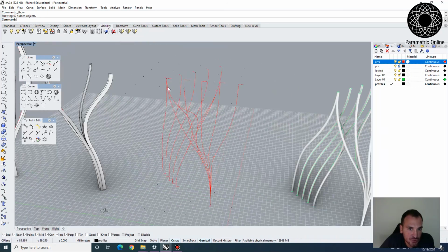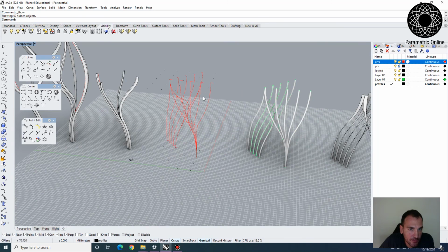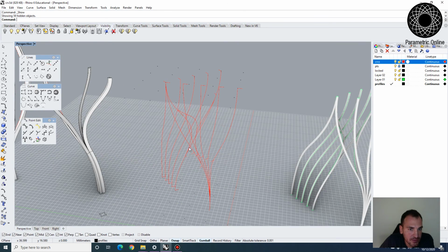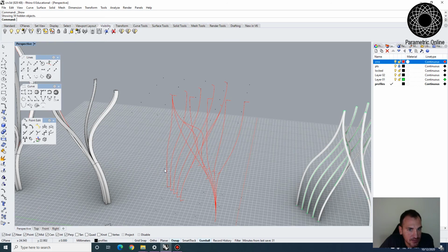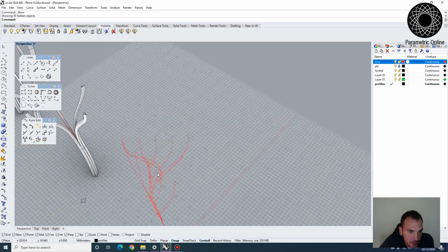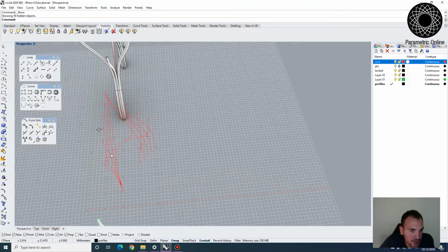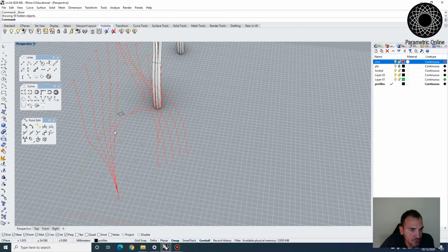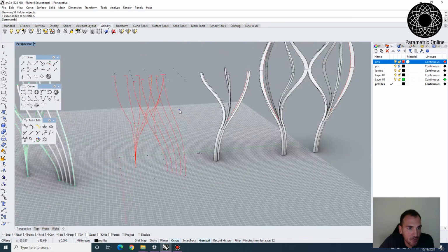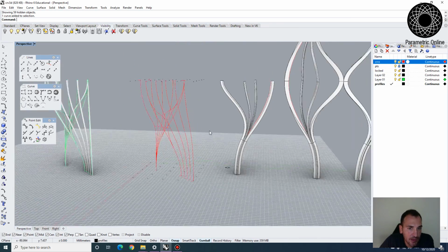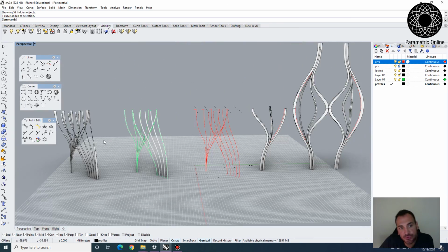And here I also showed you you can work with grids to align curves in 3D, which will have the end deviations facing in the vertical direction. And then if you want to make more connections in the middle, you can always do networking curves with this handle curve editor, but you need to draw tangents from existing curves first. And that's always a good way of building hierarchy. Then you can choose your way of thickening your figures.